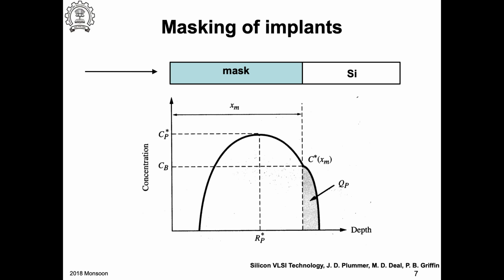So essentially you take this Gaussian and you integrate the doping concentration from this point. This is called the thickness of the mask. So if it is 0, this is xm. So xm to positive infinity. If you integrate the Gaussian profile, you get how much dopants have gone into your silicon. So that is what you are doing.